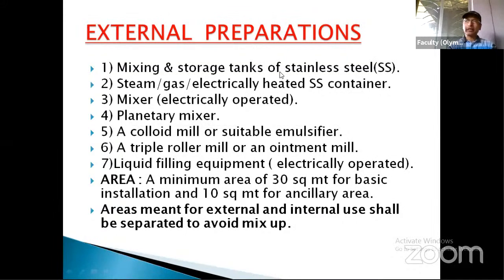Liquid filling equipment. After preparation of your external preparation, solid, liquid, emulsion, whatever may be, you have to fill it in the containers, in your packaging containers. So liquid filling equipment is needed. These are the minimum required equipments. So mixing storage tanks, stainless steel containers, which have the arrangement of heating with steam, gas, or electricity. Mixer, planetary mixer, colloid mill, triple roller mill, and filling equipment.